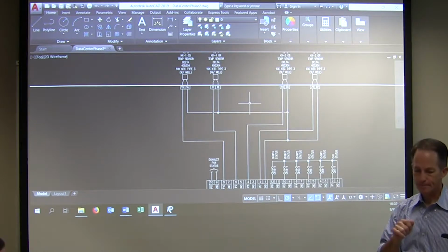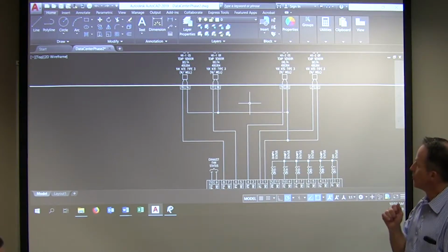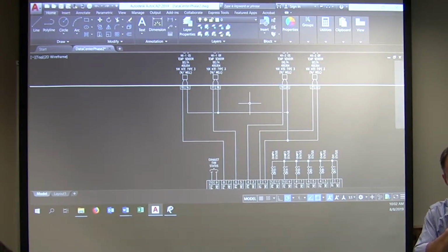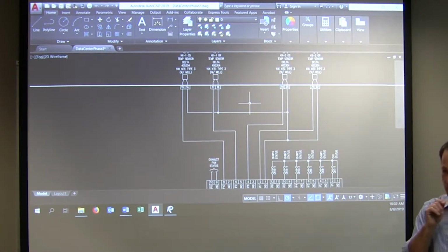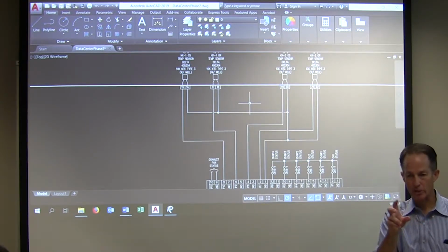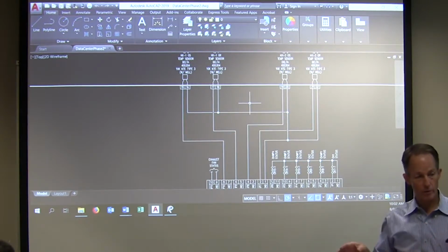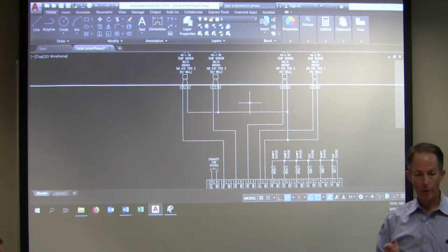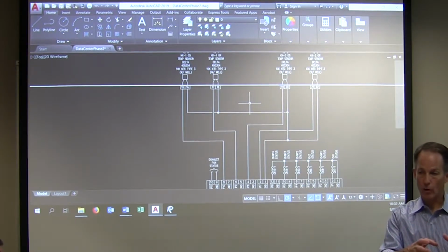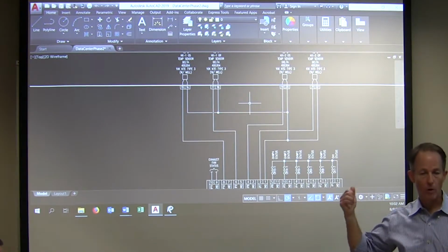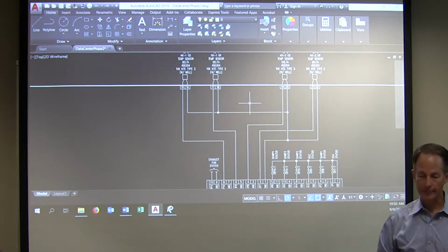Okay. All right. We're using, this reminds me of a flame sensor in a furnace, yeah, kind of similar. Okay. And we talked about there's a flame sensor that you actually use 4 to 20 milliamp. I may not have the right terminology because I'm not residential backed. Is that what it is? The flame sensor has a 4 to 20 milliamp signal? It's a microamp. A microamp. Okay. And we're going to talk about types of signals that we use, whether they're the resistive type, or whether they're a voltage or a milliamp. Here in just a second.